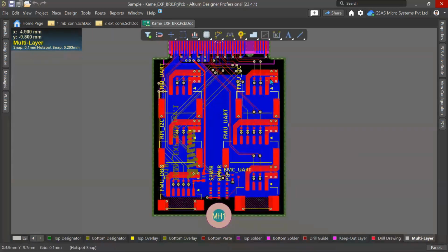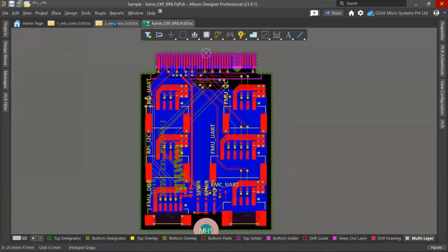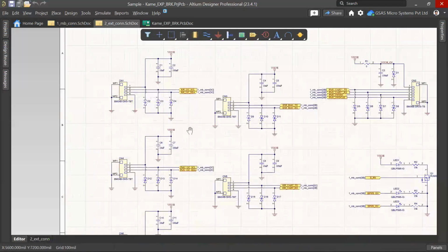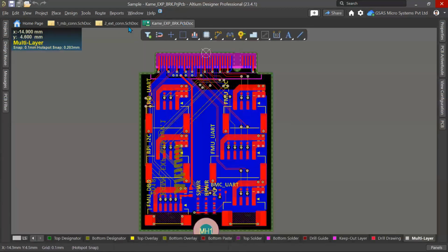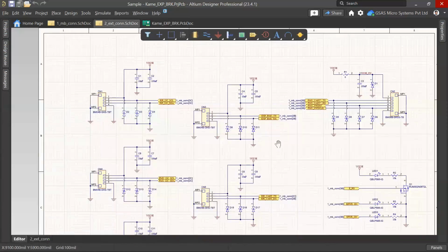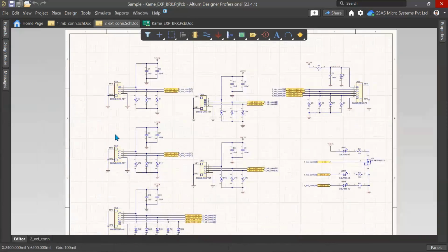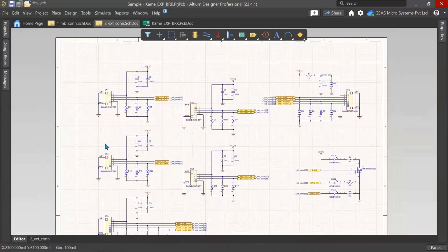First, to create a design reuse block, we have this logical explanation of this physical design. We have here the four connectors. With the reuse block, you don't need to draw multiple times, just place it four times, and automatically the placement is updated as I told.